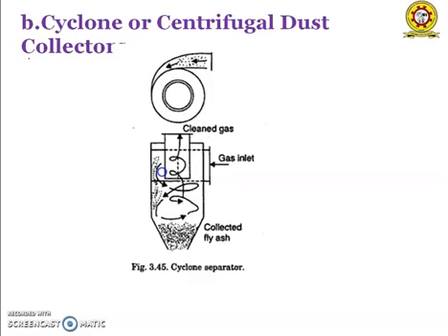The advantages of cyclone separator dust collectors are that they are rugged in construction, maintenance costs are relatively low, efficiency increases with increases in load, and it is easy to remove bigger size particles. The disadvantages are that they require more power than the other collectors, they are incapable of removing dust and ash particles which remain in suspension in still air, and cyclone separators are less flexible in terms of volume handled.